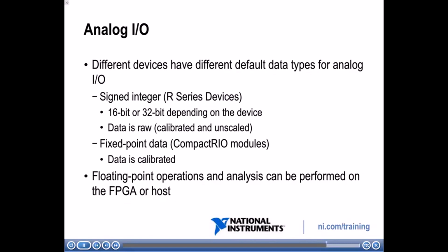So that 16-bit or 32-bit number, if you want to convert that into engineering units, you're going to have to go from that number into a voltage, so you'll have to do some scaling. And we'll talk about that more later.